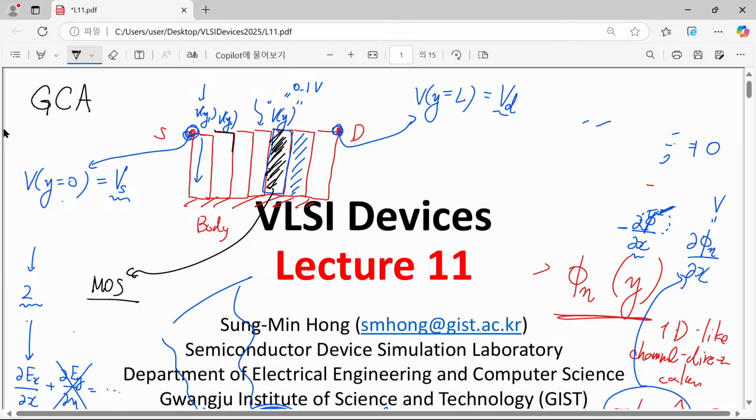Yes, here we have a different slab and it may have a different quasi-Fermi potential. Then we can treat it quite separately. There exists another MOS capacitor and its electron quasi-Fermi potential has a different value. Let's say that this one is just 0.01 instead of this 0.1. Then now we can imagine two different MOS capacitors.